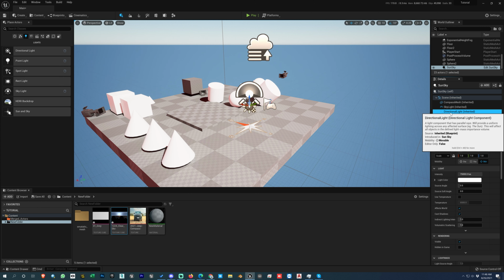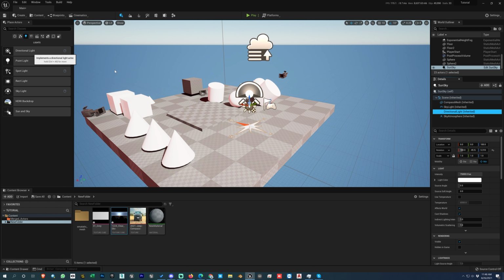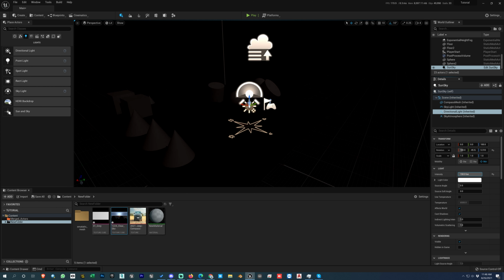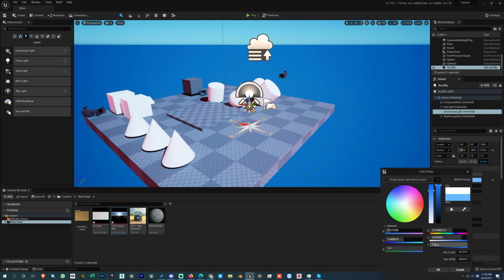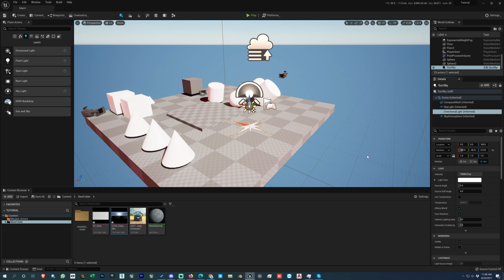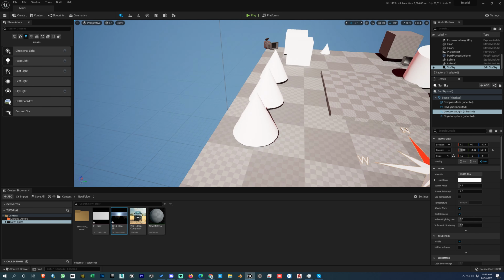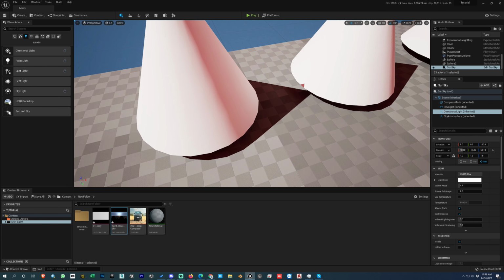And these are the directional light properties, same as this directional light, and you can change the intensity or color or anything you want. One important thing here: when this is 0.5, the shadows are very sharp, but if you make it 2, you see the edge of the shadow, the farther the shadow goes from the object, gets blurry.